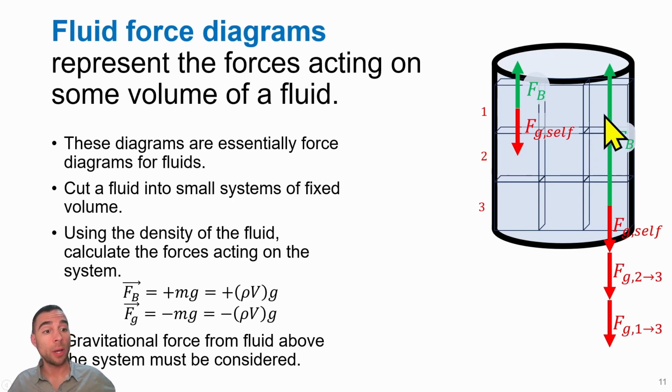Force diagrams are also a useful way of looking at fluids. You can think about a fluid itself as being individual volume cutouts of that material. Then you can think about the forces that are acting on that material, including the force of gravity from itself interacting with the Earth, as well as the force of gravity from other cutouts of the fluid above that piece that you're looking at.